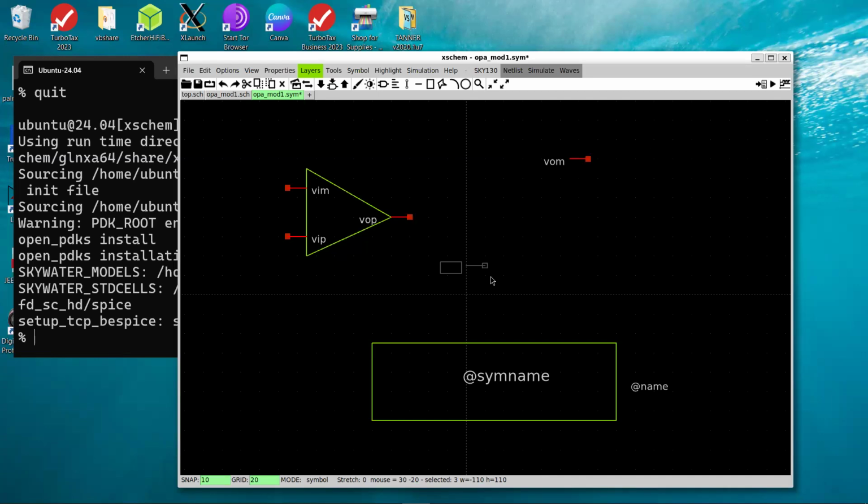I would probably avoid that because that usually is used for GM devices. So if you want OpAmp, I would say keep it triangular, but shouldn't matter. But yeah, the second pin is actually the ground reference pin, so it should be like really the ground pin.